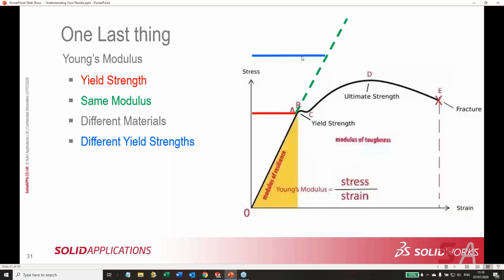the carbon steel and the high strength steel, that it's accurate for the high strength steel, and you're beyond the point where this linear modulus stress strain curve applies. So for your carbon steel, when you're way beyond yield here, all you know is you've exceeded yield. Plastic deformation, you don't know if it breaks or it bends or what. All you know is that you're beyond it. You don't know how accurate it is.